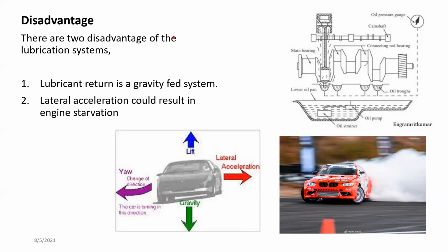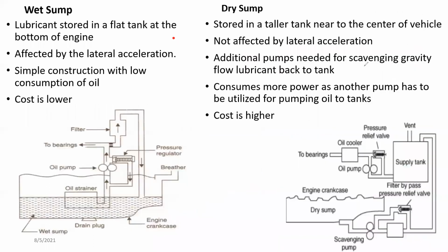Anyway, as a method to fix all of these issues, another system was developed, known as the dry sump lubrication system. The dry sump and wet sump lubrication systems are shown here. I'll start from this one. You have the oil sump here. From the oil sump, oil is absorbed through the oil pump.